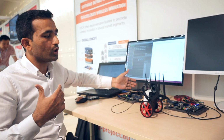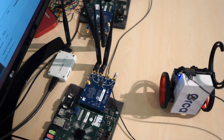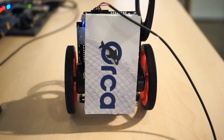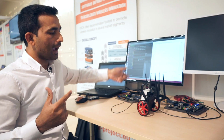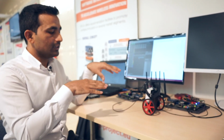This data is called balancing commands, and it comes back via UART to my robot, and based on the balancing command, my robot tries to keep itself balanced. As I mentioned, the time from this node to that node and back is really critical for the balancing algorithm. That duration is 2 milliseconds in this application. I mean, the TX slot or RX slot in the TDMA scheme is 2 milliseconds.